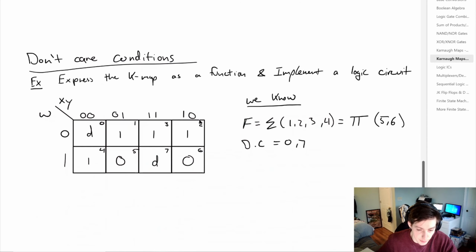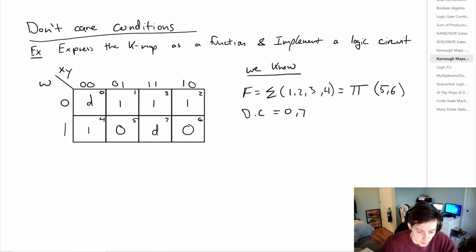Now the last thing we want to concern ourselves with is the don't care conditions, where now, in addition to the ones and the zeros in the K-map, we simply have these lowercase d's, which symbolize don't care conditions. Now a don't care condition, simply we don't care about it. Either it's not possible from occurring or it provides no output that we deem necessary to consider.